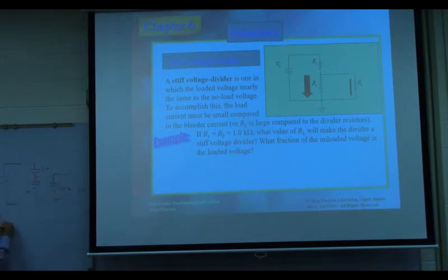Right? The output, V2 or V1, equals Vs times what is on the top? R1. We already know the numbers. R1 is 1. Over 1 plus 1 parallel to 10. Yeah, parallel to 10. Is this good? So that's 11 over 10, 10 over 11.